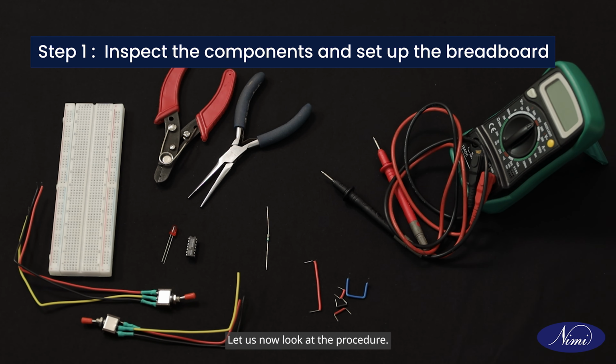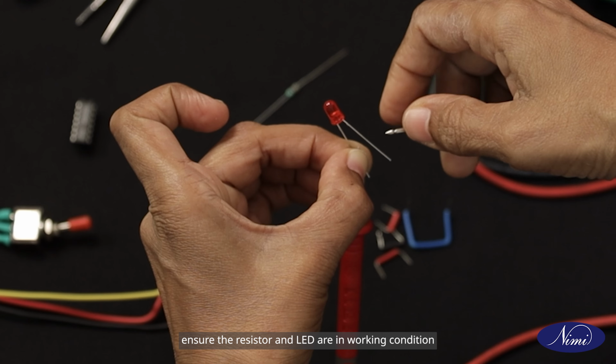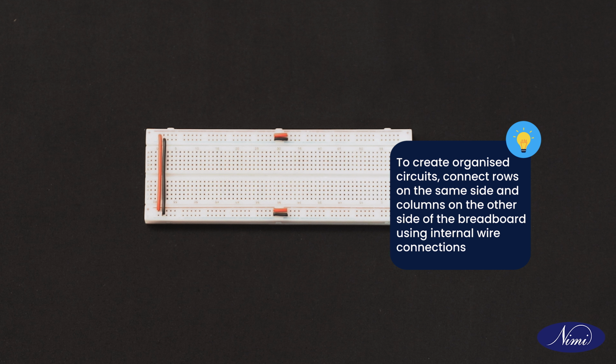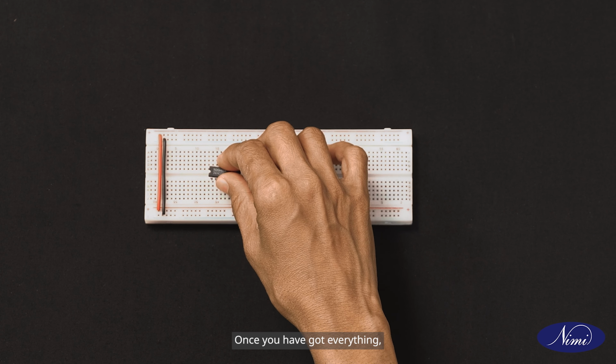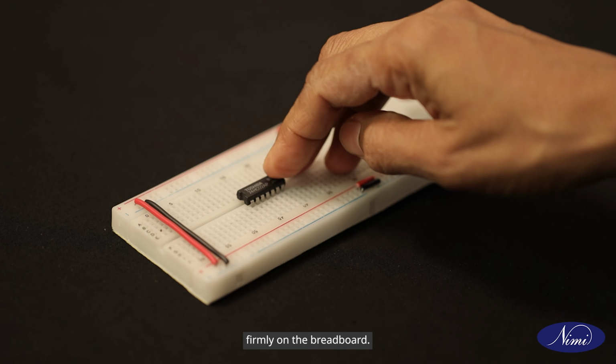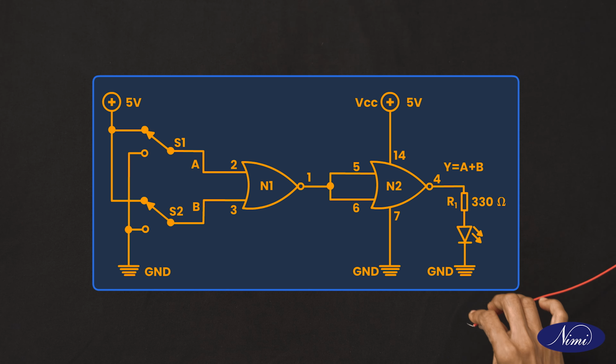Let us now look at the procedure. Collect all the required components and check them to ensure the resistor and LED are in working condition using a multimeter. Once you have got everything, mount the 14-pin IC firmly on the breadboard. Use the circuit diagram for reference.